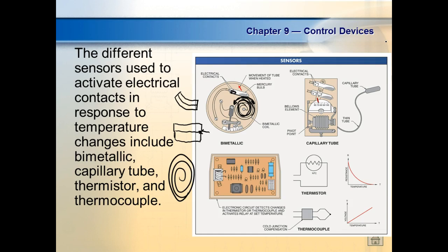Well, the way it does that is it does it with two things. It does it with a thermostat, and it also does it with a thermocouple. So gas water heaters have a pilot light on it, right? And then it's got a thermocouple that comes up and does what? Sits in the pilot light.